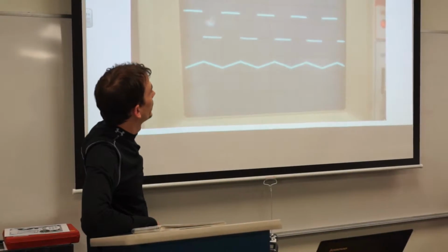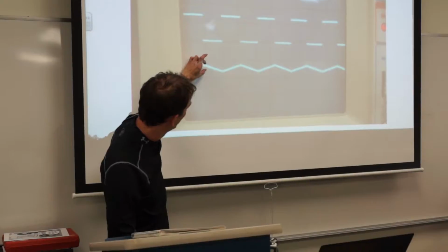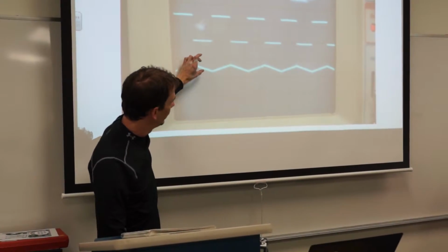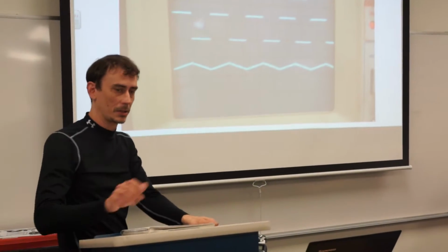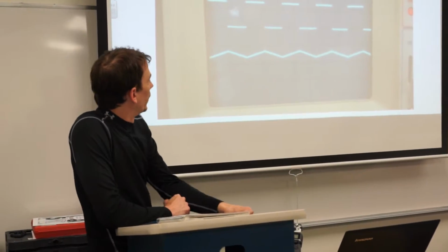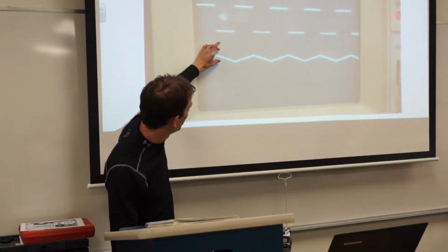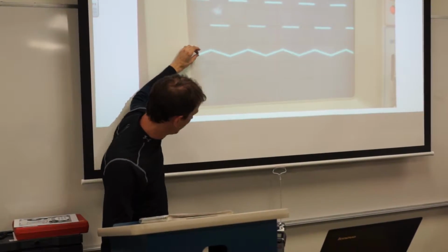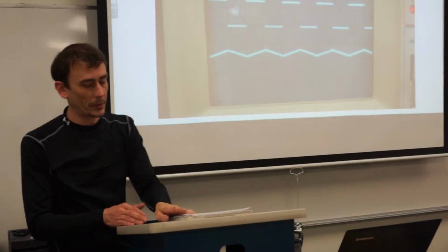So this is our final design, 50% cycle. I've got the noise scaled, I'm zoomed in pretty far here. That turns out to be right around 19-20 millivolts of noise, which is about as close as I could get it. There is some evidence that the noise technically does exceed that for micro and nanoseconds at a time. It does spend most of its cycle well within that range, so I thought that was fairly successful.